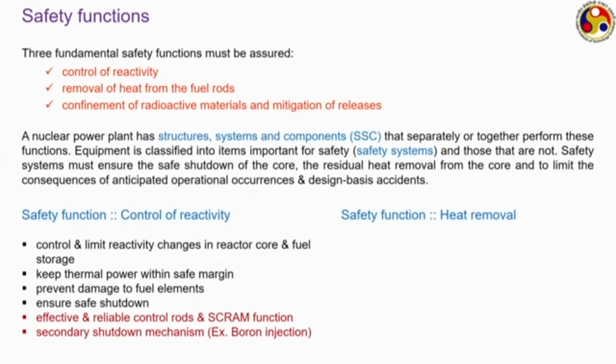Whereas when we are talking about heat removal, the coolant level and flow must be maintained inside the reactor, because any decrease in the flow rate, as I have mentioned, will result in overheating of the plant. The heat sink for residual heat removal should be very reliable. The heat transport system should be very reliable, particularly in boiling water reactors where there is a phase change involved, so we must ensure that the operation is limited to the nucleate boiling zone.